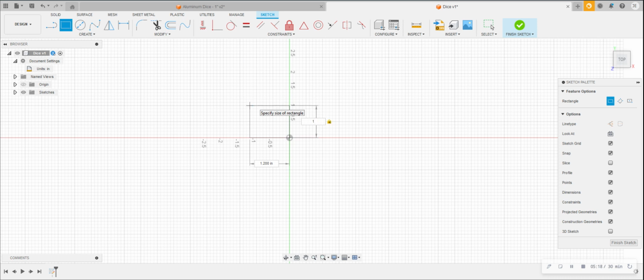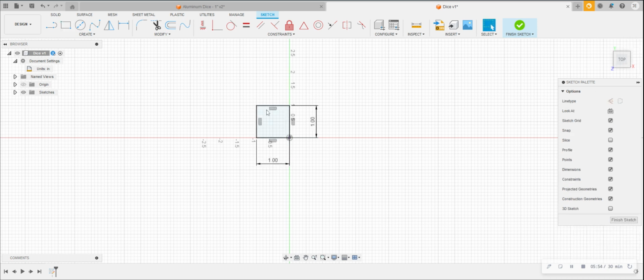Okay, once that's done, I know I need to come down and change the value that's moving, this horizontal dimension. So what I'm going to do is use my keyboard, and on my keyboard there's a key called Tab. I'm going to hit that and it will automatically take me over to the other value that right now says 1.146. I'll overwrite that by typing 1 on my keyboard. Once I have both of these values locked in the way I want them, I'm going to hit enter on the keyboard, and now I have the rectangle that is sized the way I want it to be.